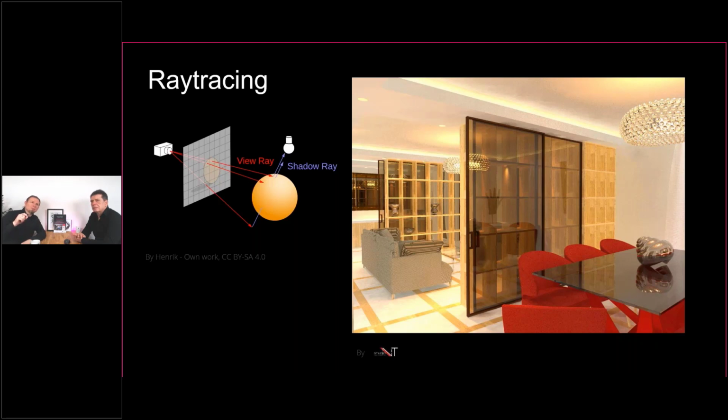And there comes another visualization core, not a calculation core, connected. This is Enscape, and Enscape is something in between. Enscape makes it possible to go into the scenery. You can walk through the scenery and move your camera freely, and you also have this close to ray tracing calculation method with transmission and reflectance, but in a game engine way.